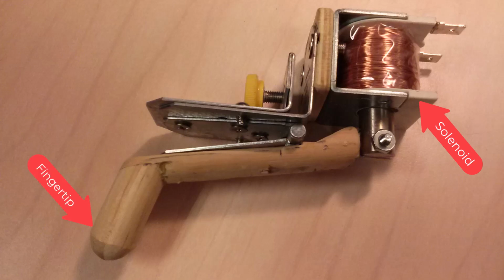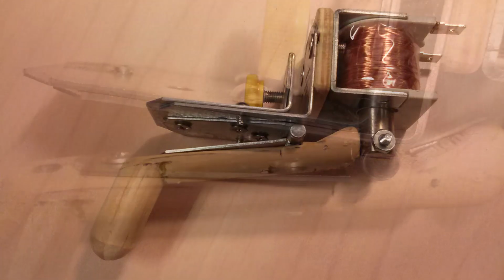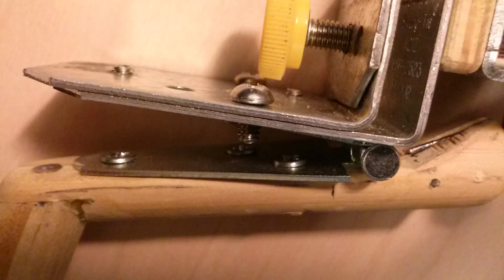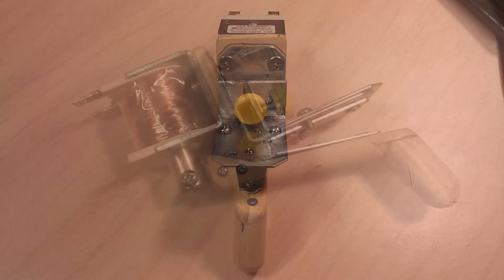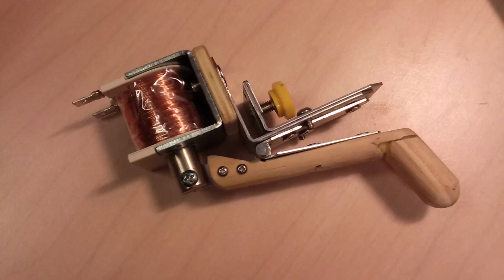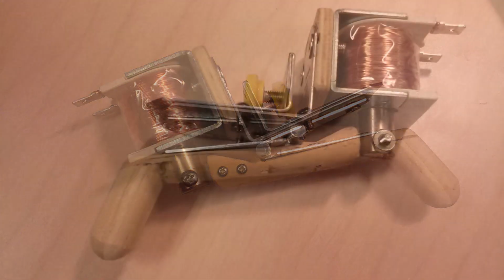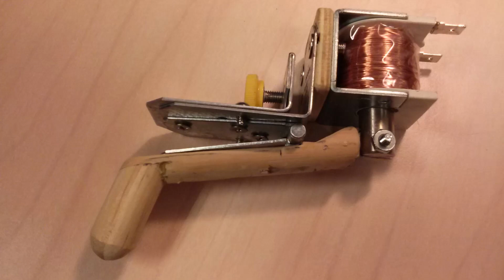So these were electrical, and so therefore, when you did the emissions testing, which is testing to see if this thing is radiating at frequencies that would stop your pacemaker and interfere with other equipment, which is obviously bad, when you're doing that type of testing, you can't have other electrical signals around other than the equipment that you're doing the testing on, right? Makes sense. So I came up with this pneumatic system to do the touches.